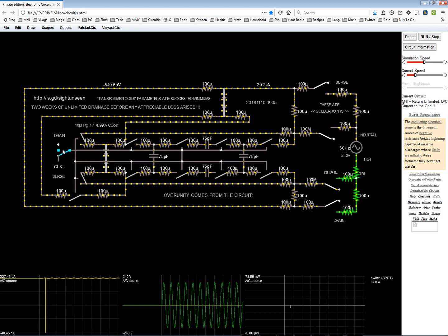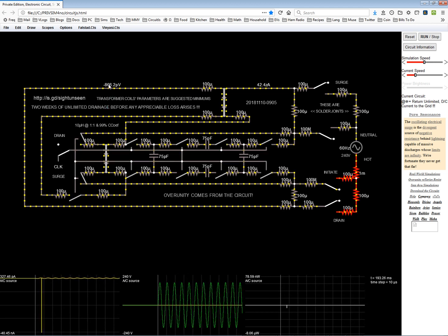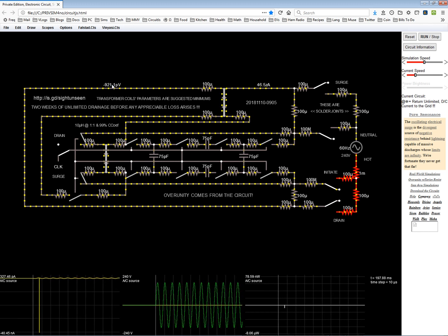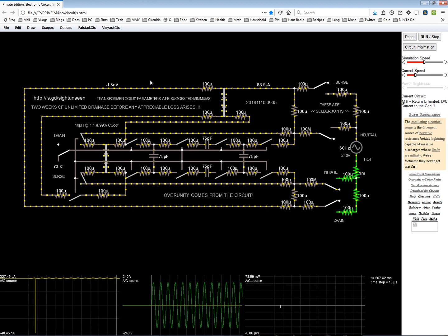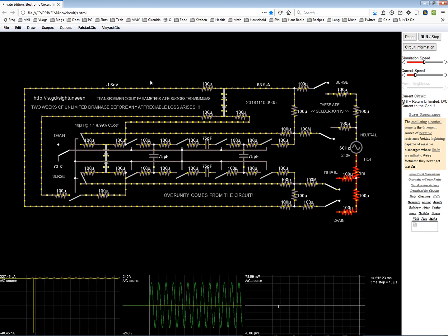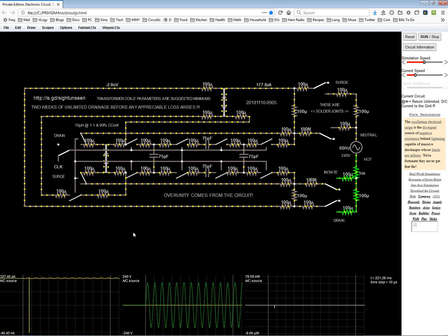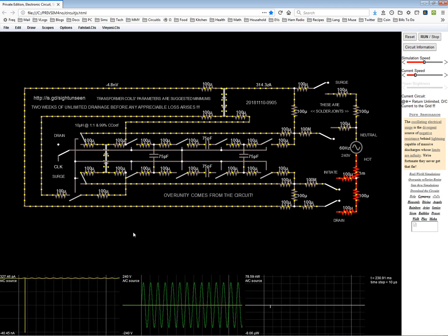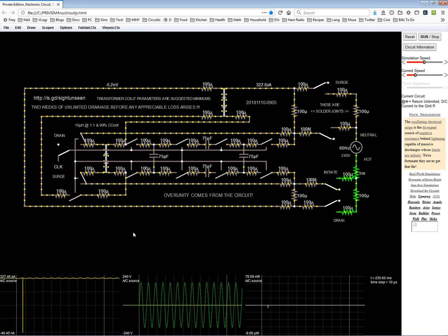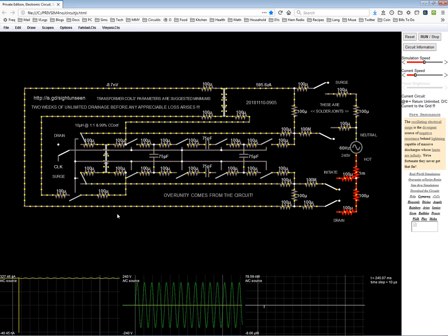Now, I increased this cycle time in order for these incremental jumps, increases, to be at a reasonable rate, so that you can fine-tune how much amps you want to deliver back to the grid. Otherwise, you end up with wildly different figures, too much and too little. But I had to do it this way.